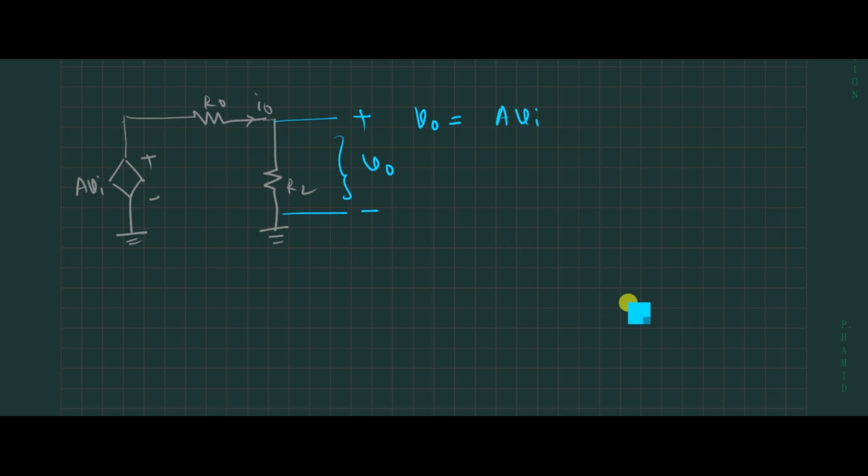It is a load resistance. It is an external thing which we are going to connect to the amplifier, that will exhibit the loading on the amplifier. But here R0 is part of the amplifier circuit. It is the DC resistance looking into the circuit from outside.